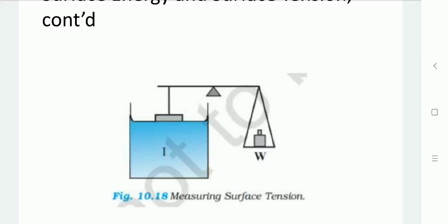So here, for cohesion between a solid and the fluid, we need to consider a vertical glass plate below which a vessel of some liquid is kept. This forms one arm of a balance to measure the surface tension, as you can see in the diagram. The plate is balanced by weights on the other side with its horizontal edge over water.